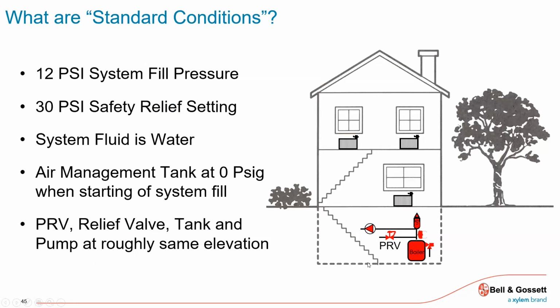Expansion tank, you know, I'm not going to have any water in that tank. I'm just going to have air, the air charge, which has to match the system fill pressure, which we just talked about. So residentially speaking, those diaphragm tanks, we have hundreds of them out back, and all the other tank manufacturers distributed throughout New England here, they're all coming from the factory pre-charged to 12, just because the majority of the applications are a 2-story building.